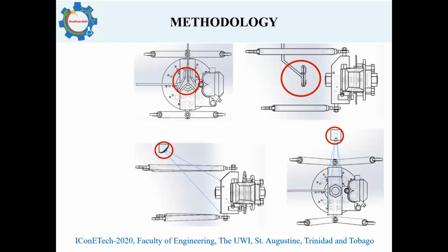Here we just briefly are going to look at some of the alternatives that we used. So the first being an acoustic sensor. The acoustic sensor would measure differences, changes in distance between multiple positions, and that would in turn give values for camber, caster, and toe. Similarly here for the optical version, it keeps an eye on the surface profile and then monitors changes in that.